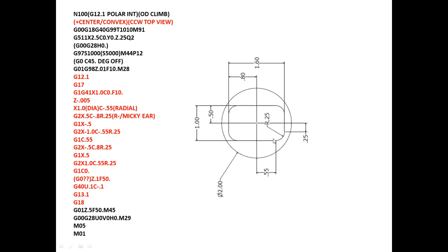Okay. Polar interpolation. Let's say we did the face milling all the way around with this programming example, but I wanted to rotate this shape at a 45-degree angle, because I got another cross hole, the timing is different, so I need to move this shape 45 degrees. What you can do is simply go, you can see my cursor, there's a G0, C45.